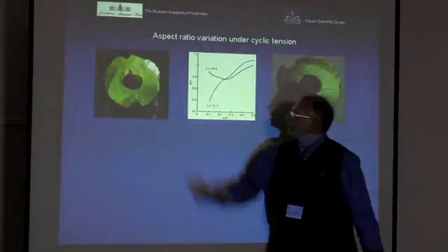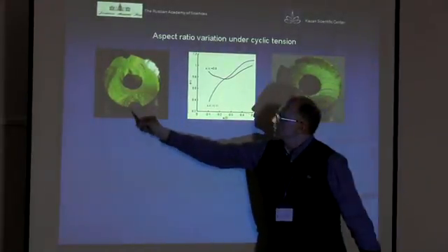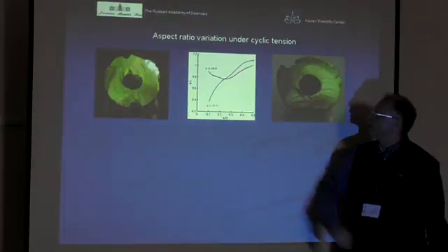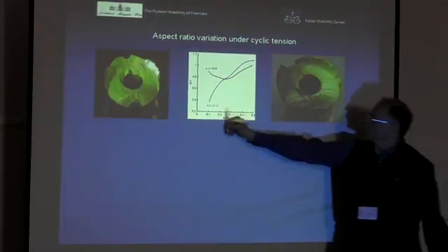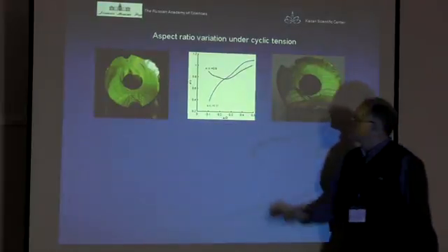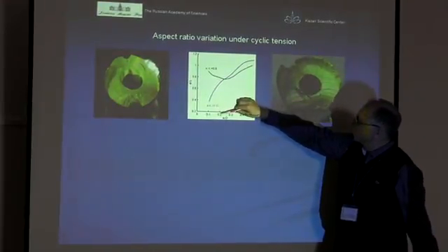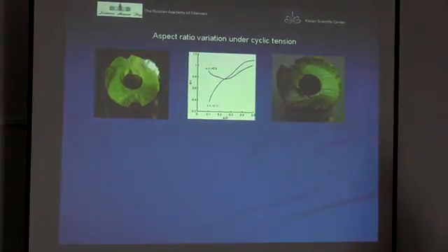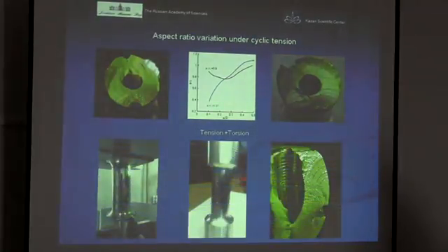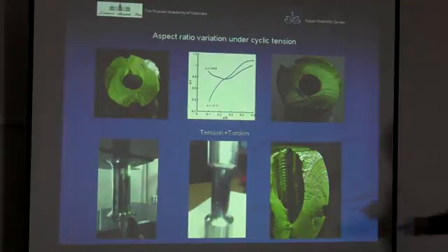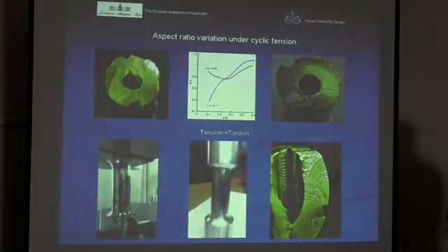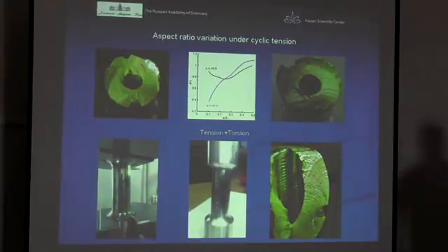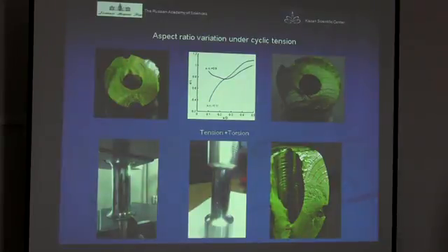For these types of initial flaw, and initial flaw with aspect ratio approximately 0.7, you see that when dimensionless thickness is approximately 0.25, both curves approximately coincide with each other. So now I would like to show you crack paths under tension and torsion loading, and again, crack front position as a function of accumulated number of loading cycles.